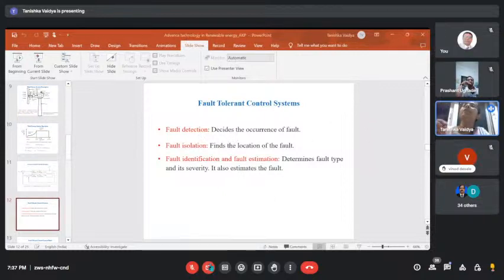To identify all the various types of faults, particularly control system faults like sensor failure or actuator failure. Because if the automation fails, definitely the system will fail. If some small fault is there in a mechanical part, it will not abruptly fail. In between, maintenance will happen, and in that maintenance, that fault will be cured. But if automation fails, definitely the structural failure of the wind turbine will occur.